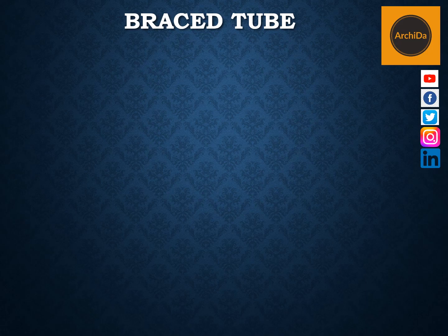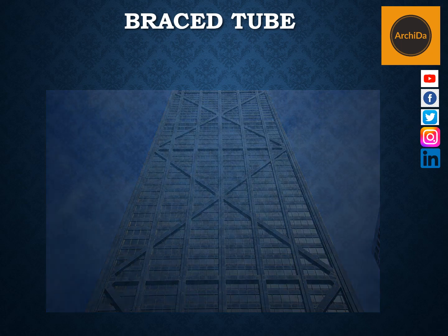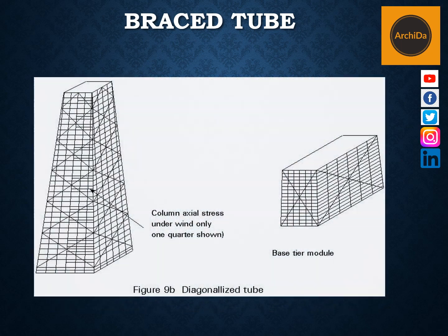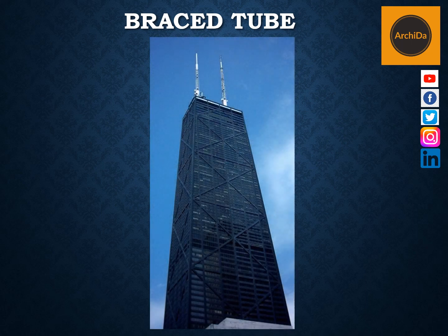The next type is called the braced tube, which is also known as the diagonalized tube. It has fascia diagonals. The advantage of this is it eliminates the closely spaced columns of the frame tube, and is suitable for multifunction use since the interior is now free from structure for resisting wind action. For the braced tube, check out the John Hancock Center in Chicago, done in 1970.